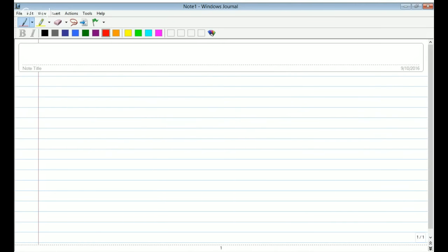So the basic reason is that the open circuit test is conducted at rated voltage and the short circuit test at rated current. If we want to apply rated voltage, it is easier to apply a lower voltage than a higher voltage. That is why we apply the rated voltage on the LV side and open circuit the HV side. When it comes to current, we have to conduct the short circuit test at rated current. Obviously, at the high voltage side, rated current will be less, and at the low voltage side, rated current will be more. That is why we prefer the HV side for conducting the short circuit test, so that the amount of current required is less and can easily be obtained. That is the primary reason.